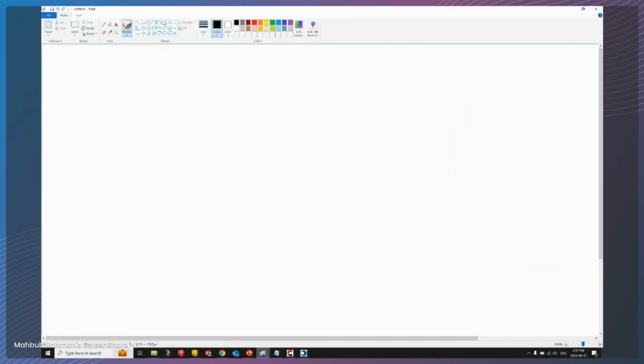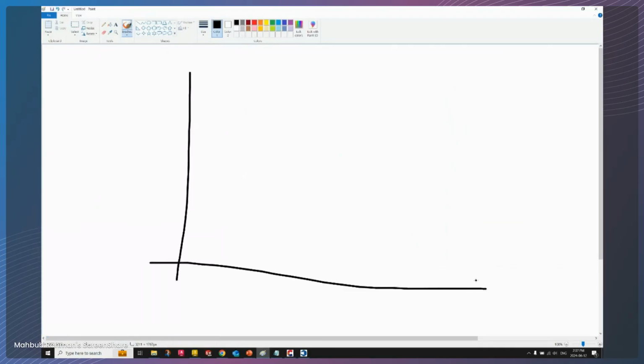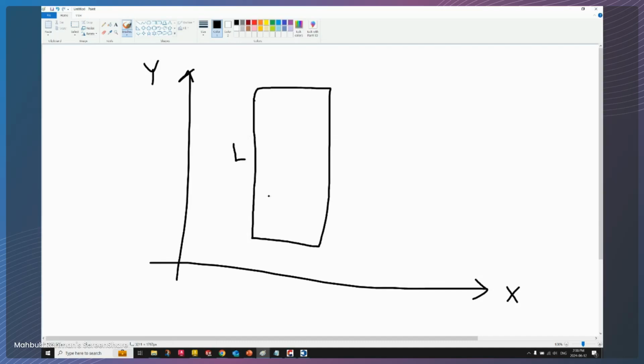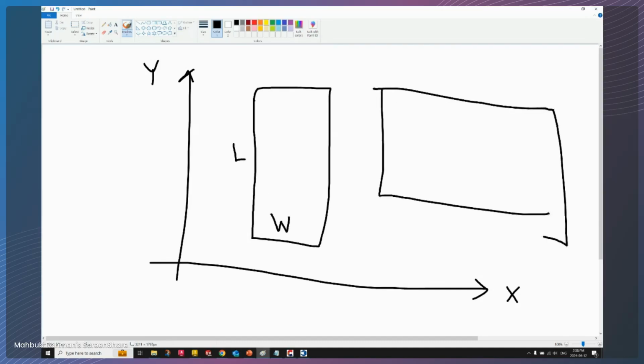One of the things that I forgot to mention is how the software will be creating plates, how the software wants to see the plates placed on your model. If you're working with plates, the only requirement that we want to see on the plates is that you place them with length and width on this XY, or width and length, it doesn't matter, right? So that's length and width.